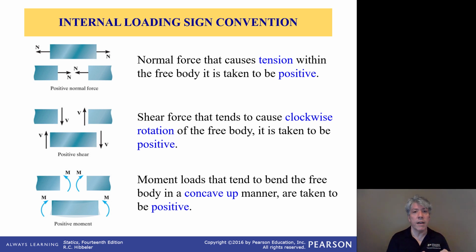Now, we'll often still have XY coordinate systems, and we'll still sum forces and moments according to that coordinate system, but when we make our shear and moment diagrams, we will want to consider the axis of that diagram and what is positive or negative. So it kind of makes sense that tensile loads would be positive, and compressive loads would be negative. That way we can easily differentiate between the two.